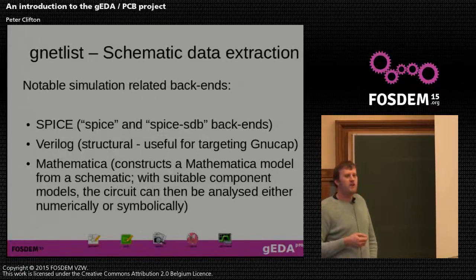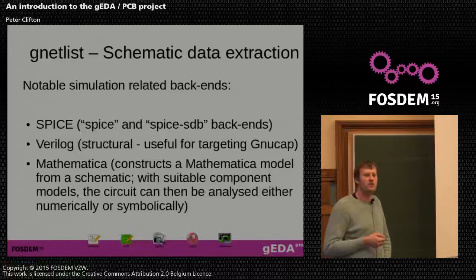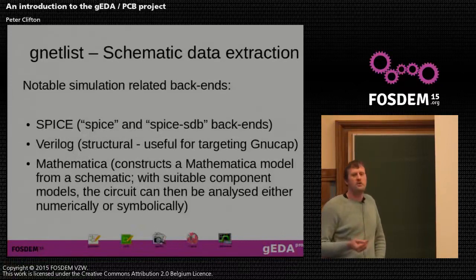If you're targeting GNU-CAP, what you want is Verilog, a structural subset of Verilog, which is used to connect up the different models. GNU-CAP has the inbuilt models, the behavioral models that you'll actually be using for the simulation, but you hook them up with structural Verilog.